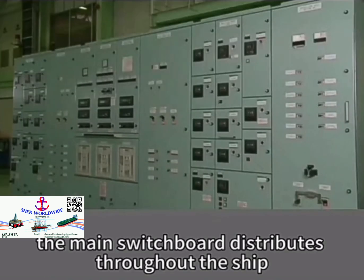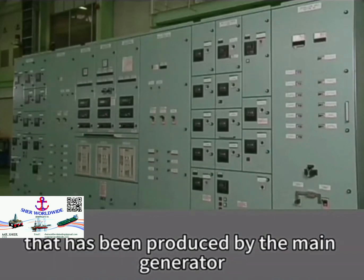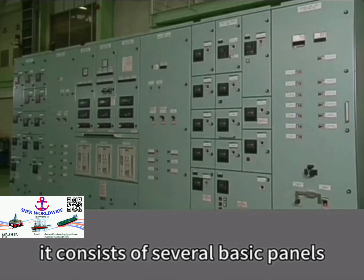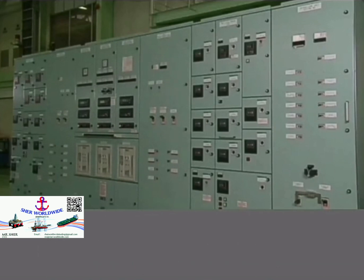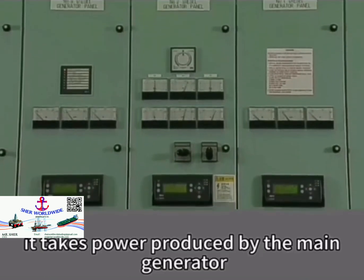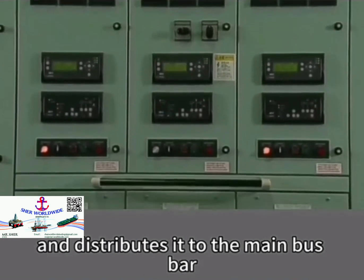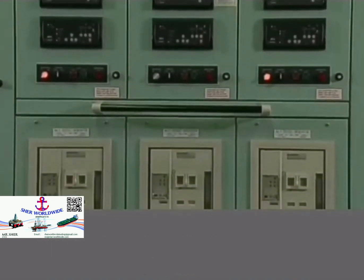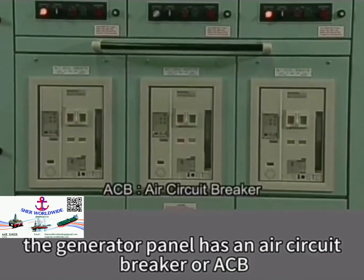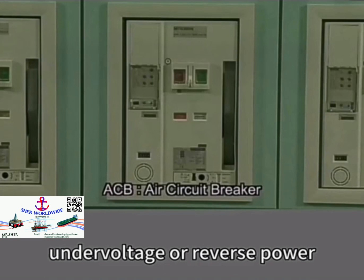The main switchboard distributes throughout the ship electric power that has been produced by the main generator. It consists of several basic panels. This is a generator panel. It takes power produced by the main generator and distributes it to the main bus bar. The generator panel has an air circuit breaker, or ACB, that trips off the circuit in the event of overcurrent, undervoltage, or reverse power.